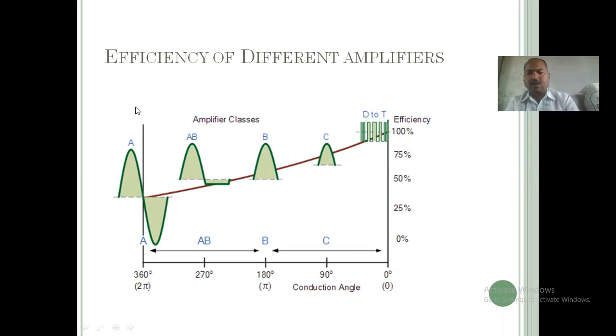So that's why we design another type of amplifier, that is the class AB type of amplifier. In that amplifier, we apply some biasing voltage. The biasing voltage is the voltage applied to the transistor, which causes the transistor to operate for greater than 180 degrees and less than 360 degrees. So during that small period there is conduction of the transistor, and whatever input power is applied comes across your load, so no crossover distortion occurs. This happens in case of the class AB type of amplifier.